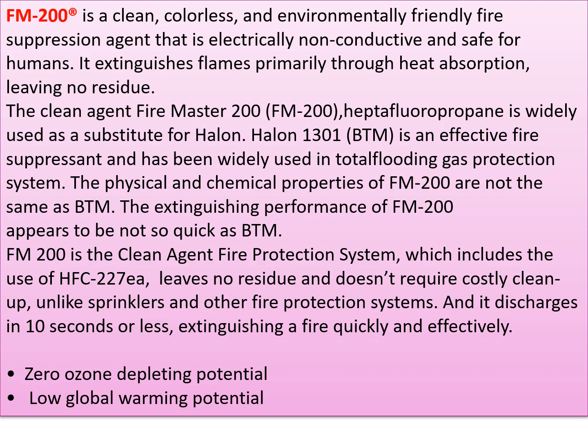One of the very effective clean gas total discharge systems is known as FM 200. It's a trademark. FM 200 is a clean, colorless, and environment friendly fire suppression agent that is electrically non-conductive and safe for humans.